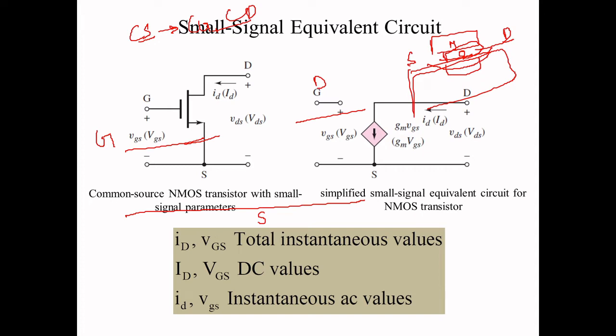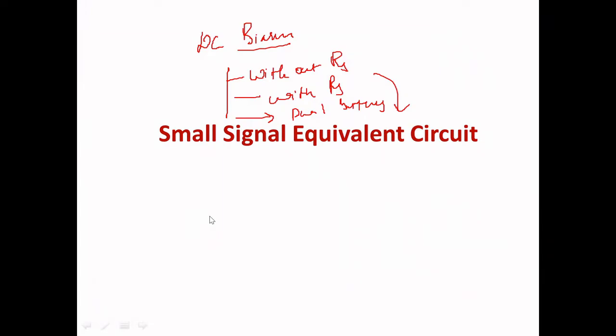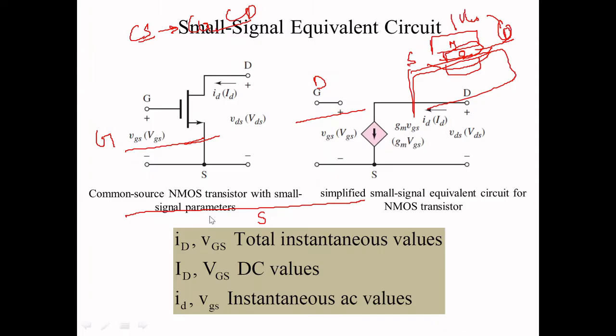The principle is the field effect, which is why it is a voltage controlled current device. The input voltage VGS controls the output current ID. So it has a higher input impedance, and that is why it is represented by an open circuit.